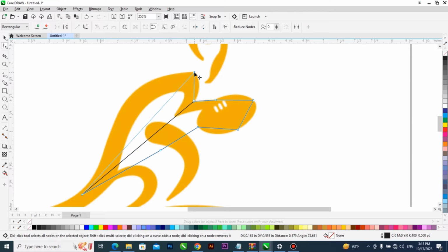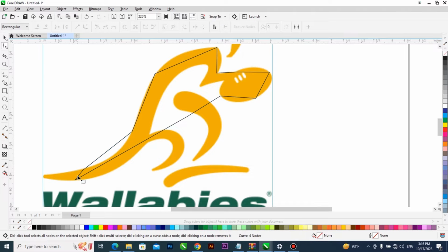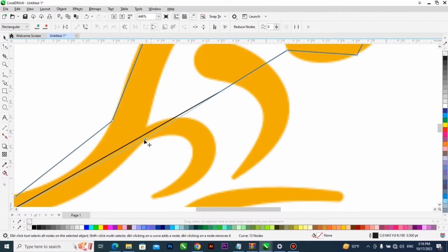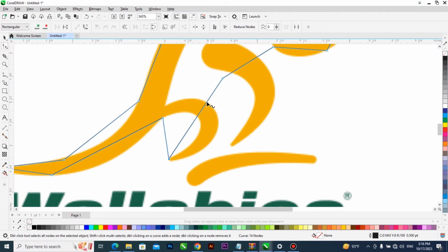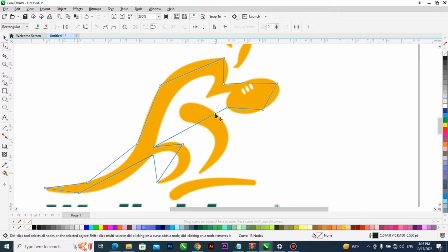What you need to do is, I prefer using the freehand tool, and on using that freehand tool I should be able to use the easiest shaped freehand tool in doing my logo tracing, which is the bezier, the invisible line that follows the mouse pointer wherever you click. So very quick one, I'm setting an anchor point where I would like to curve or turn to line.